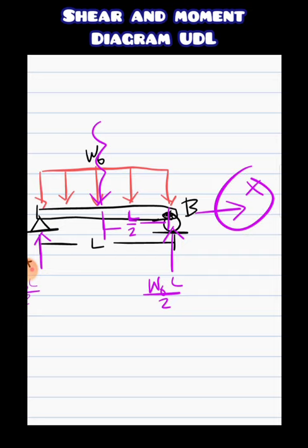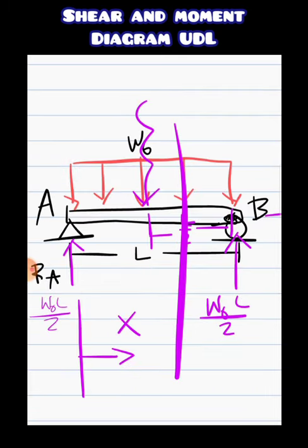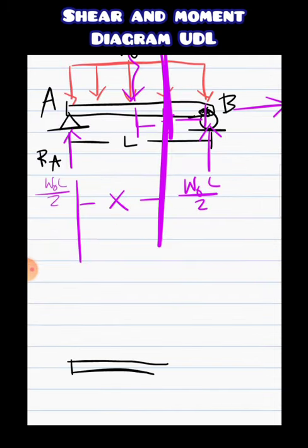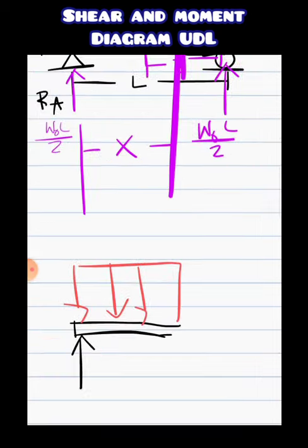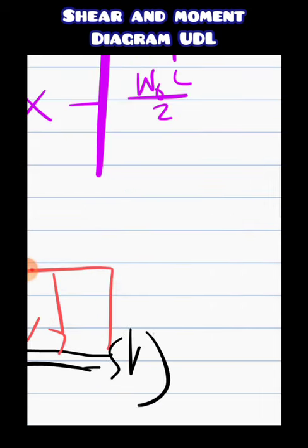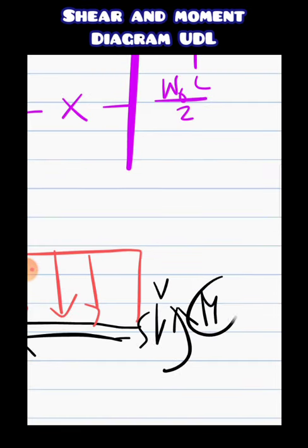This is our x. And we will run an x-axis about these sections. Right? This is going to be our x. We will cut this and expose its internal reactions. Of course, when you expose a beam, in order for this beam to balance out these forces, it must have a reaction, positive in this direction. This is now the internal shear, and this is now the internal moment.